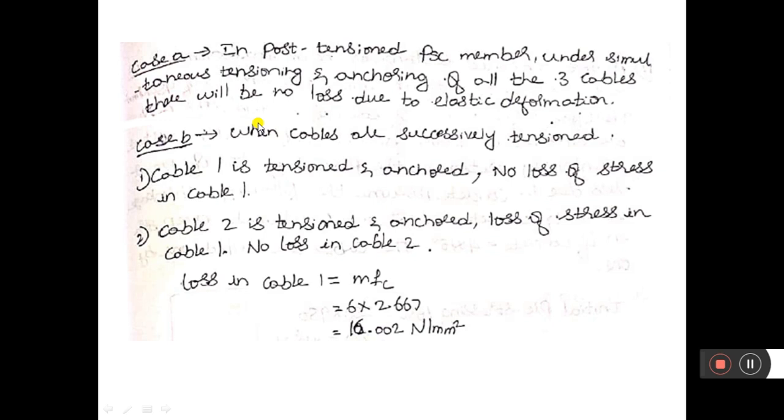So first let us consider case A, that is all the cables are pulled together. So cables are simultaneously pulled. When all the cables are pulled together, the loss due to elastic deformation or loss due to elastic shortening will be 0.